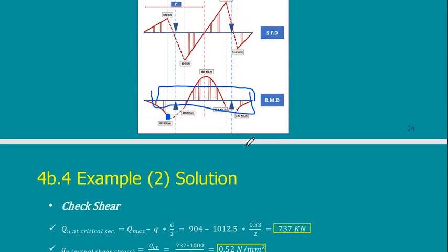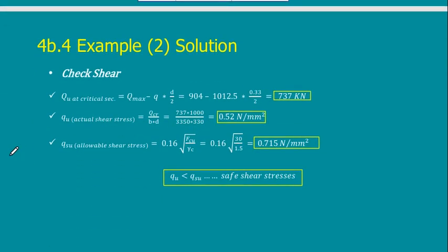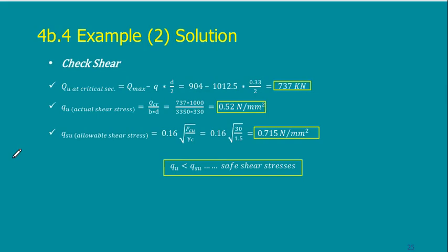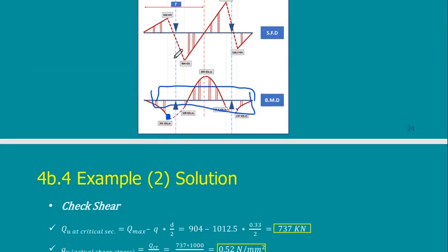But before I proceed, as we said, we need to check shear and punching. Why do we need to check shear and punching? Because if we do not check shear and punching, maybe the footing is unsafe, and the only thing I can do if the footing is unsafe is to increase the depth, and in this case the calculated amount of reinforcement will be reduced. So it is better to wait, not to design the amount of steel except after checking shear and punching.